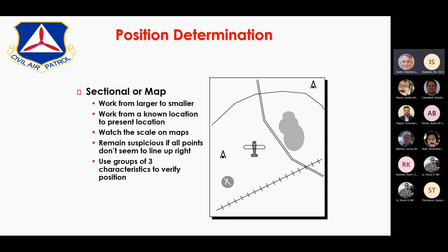People argue the other way, and I can see where if you've trained yourself to go with a track up orientation of your charts, then that could work for you as well. But just make sure you've thought about it and chosen the one that works best for you and use that consistently. Again, cross-checking everything is the most important thing so that you don't accidentally get lost in the middle of flying something, so that you can react to new information and so that you won't be distracted.